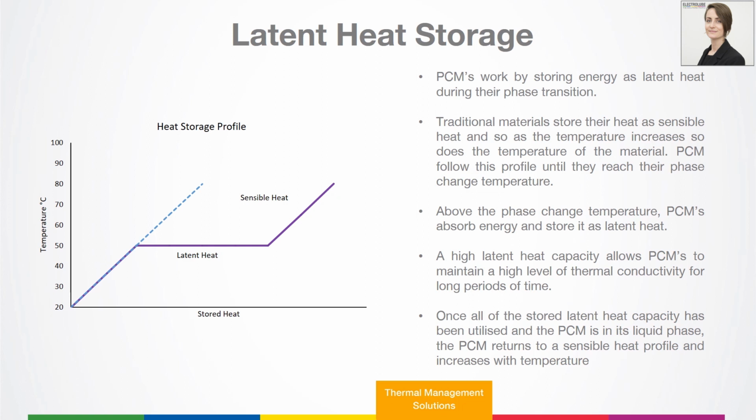Typically what happens is that materials store their heat as sensible heat. So every time the temperature increases, so does the temperature of the material. Phase change materials follow a slightly different path though, as indicated by the purple line on this graph. They're used to absorb peak energy loads when a device is switched on, and then they release it at another